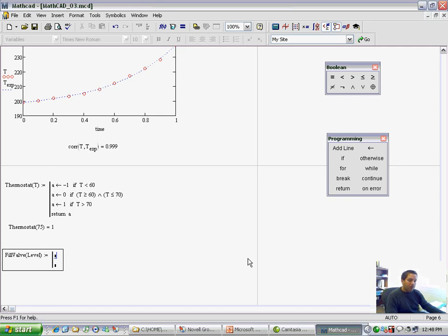So we're going to say A, which is a local scope variable again, and we're going to set it up to, in quotes, open, if the level is less than 5. If the level is less than 5, then open the valve to fill up the tank. Then A is set up as close. We could say if the level is greater or equal than 5, but we can just say otherwise. It will be identical.